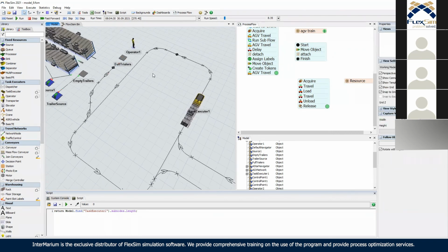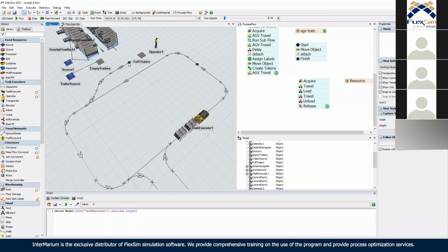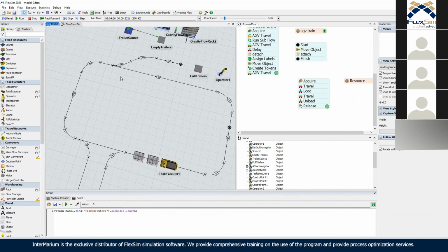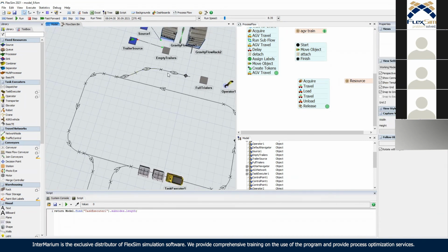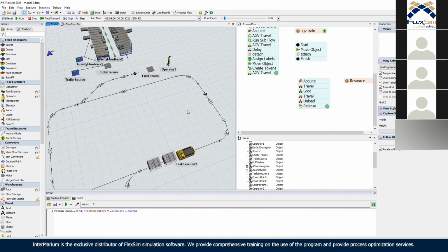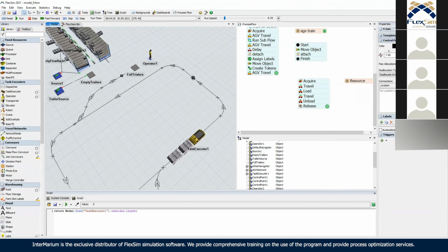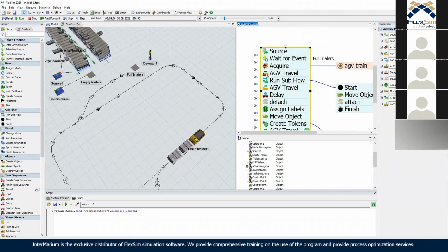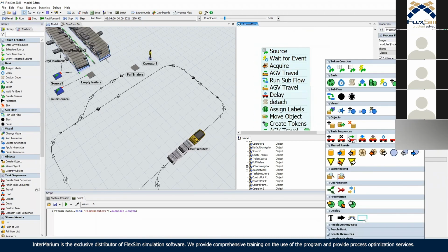And this lets you easily create logic about, for example, you can only have one AGV here. So hold this, let's say, line of approach has to be always clear, because if 2 AGVs go there at the same time, they will deadlock. And so you also have to think about what the logic of movement is in your AGV network. Okay? It can be easily detailed with more control points. Yeah? You can have a control point here, and you can have a control point, let's say, here. Yeah? And just before the first travel,